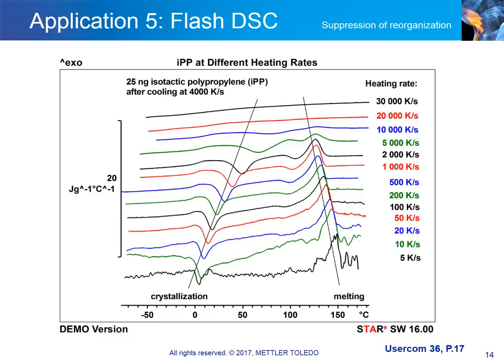If a semi-crystalline polymer is measured with a conventional DSC instrument, the DSC curves generally exhibit a glass transition whose step height is proportional to the amorphous material content, and an endothermic peak, which is related to the melting of the crystalline component.